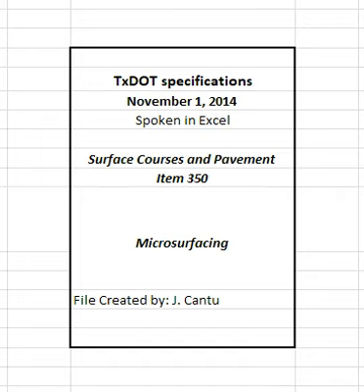Calibrate and properly mark each control device that proportions the individual materials. Equip the aggregate feed with a revolution counter or similar device capable of determining the quantity of aggregate used at all times. Provide a positive displacement type emulsion pump with a revolution counter or similar device capable of determining the quantity of emulsion used at all times. Provide an approved mineral filler feeding system capable of uniformly and accurately metering the required material.